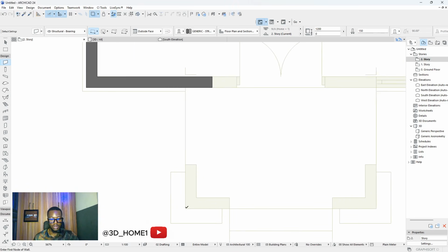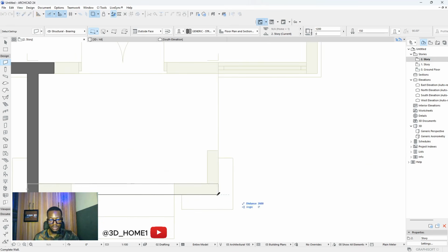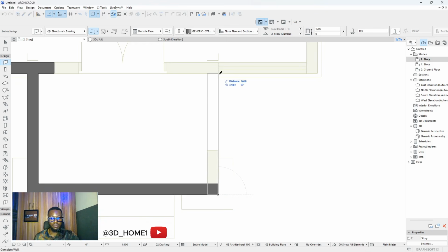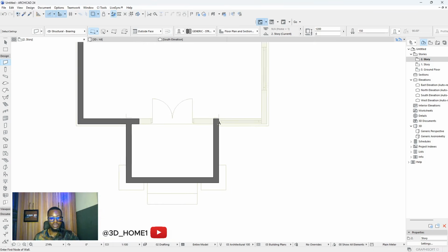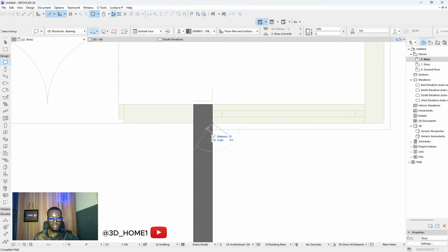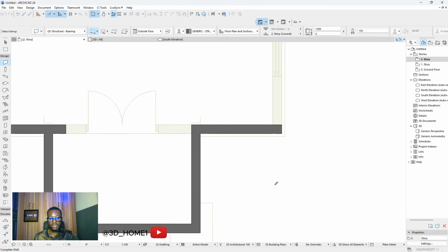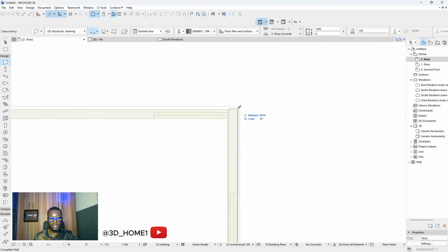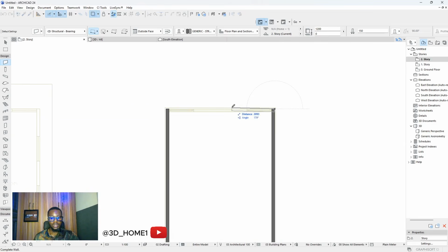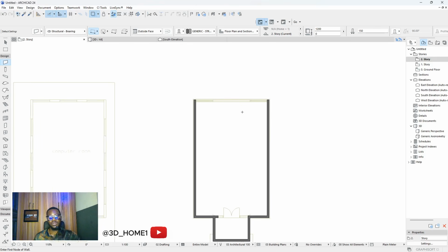Okay, so here, if it's outside, press P, like P for person. Okay, P again. Let's take it inside. But if you want to do working drawing, I would advise you use center to center. Okay, center to center from here to here. Then we take this one all the way back to this point. Then take this one. No, let's leave it like this because the roof will be sloping all the way back.